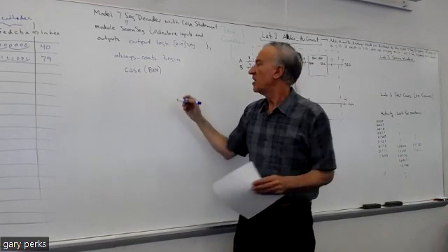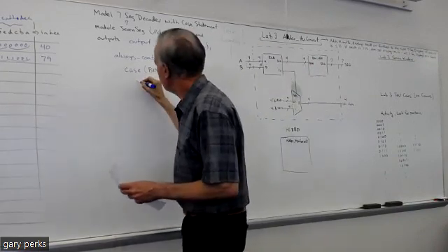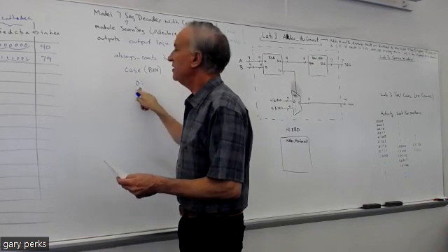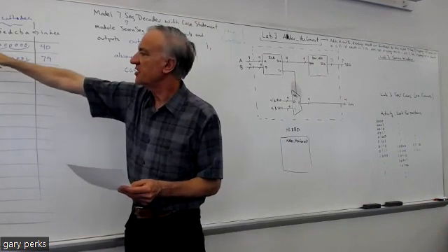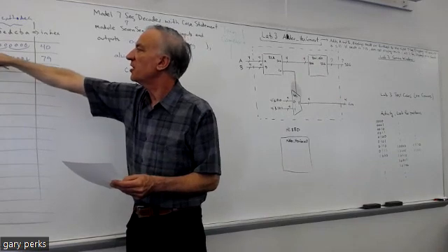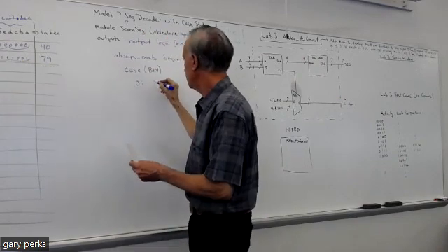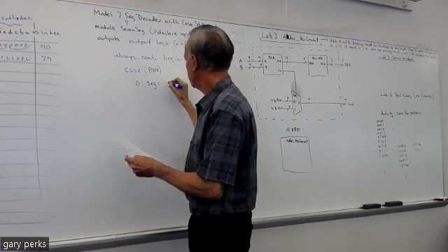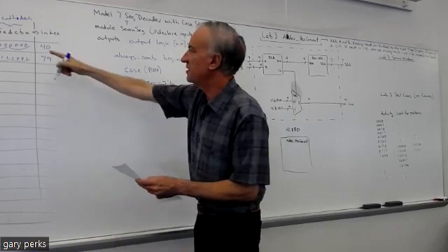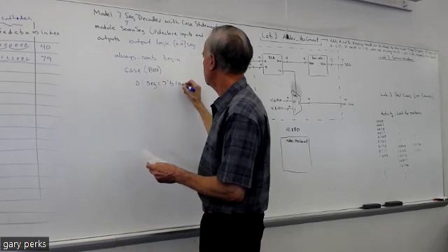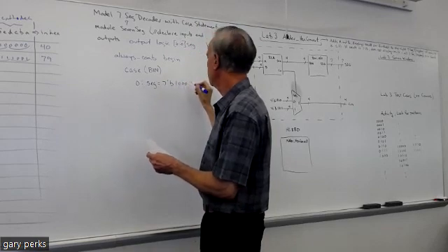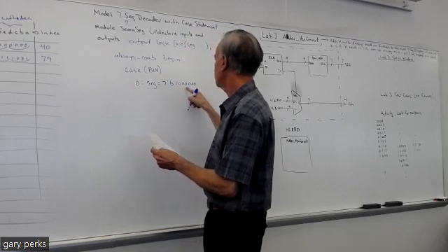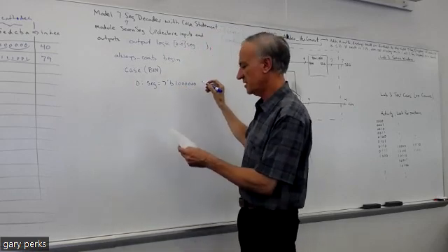All right, and then you just put 0 for the first case here. It always starts with 0. So our first case is going to be, we want our seg output to equal 7 tick mark B, and then we just put the bits. So 1, 0, 0, 0, 0, 0, 0. Let's see, is that right? That's 6 zeros. And then semicolon.